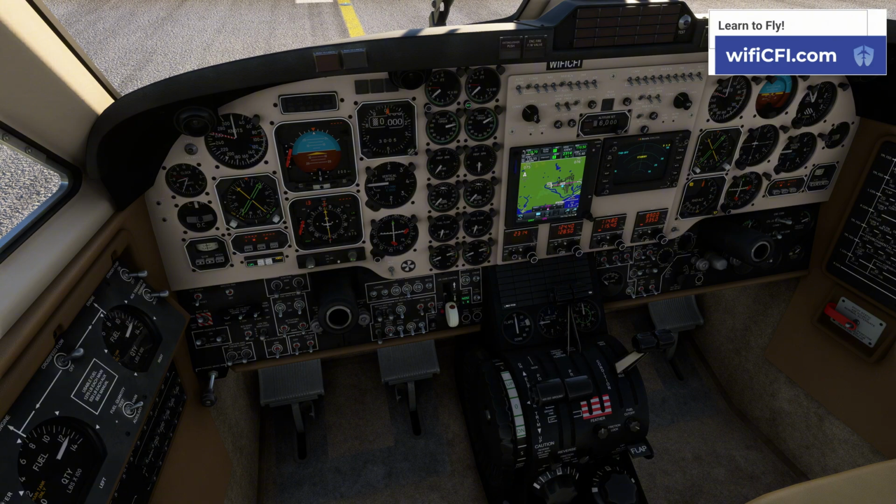And then we'll bring these back and let go of the test switch. We'll get this back up to arm. Looks good. So, yep, then we have our auto feather armed. We could then go ahead and test our feather with the actual levers here. We could get these back to feather, make sure it's working. Doesn't go to that detent with the sim, that's okay.